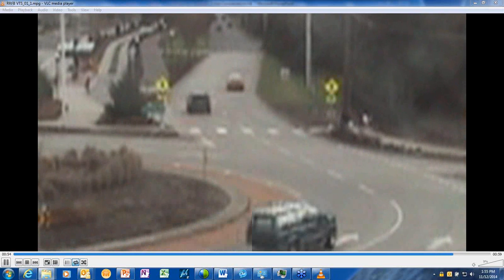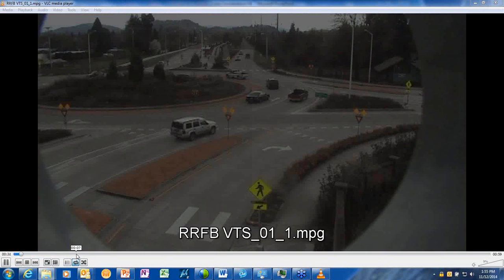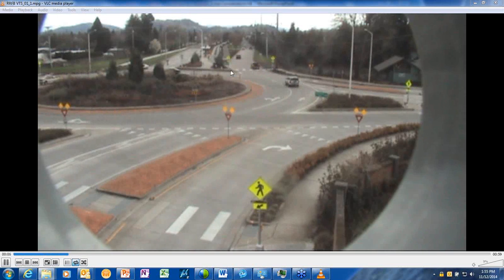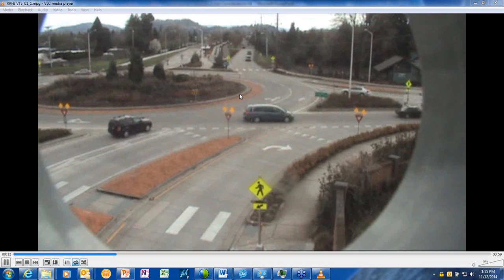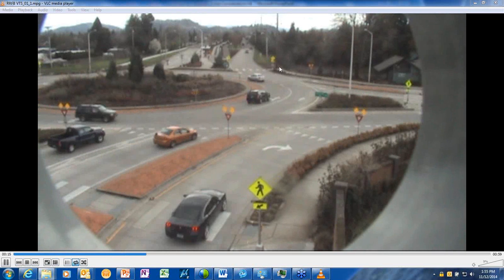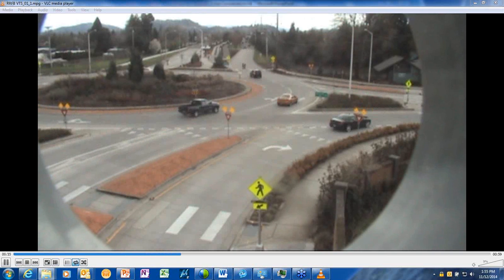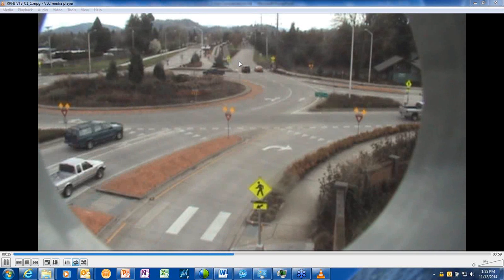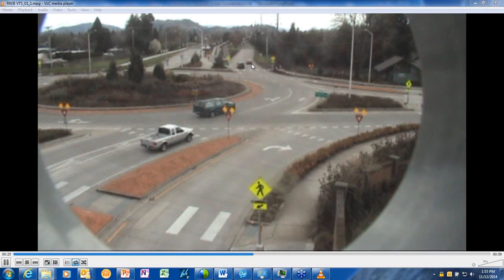The difficulty with this device is its location proximate to the roundabout, how close it's located, whether it's in the conventional crosswalk location or if on the exit it should be displaced. I don't have this video handy, but I have another clip of video from the ground level where the pedestrians are not pushing the button, or if they are, they're just walking without looking at the traffic. And traffic comes from the roundabout and is dealing with the turning movements and other vehicles, and the driver just looks up and almost hits a pedestrian. So again, more devices doesn't necessarily improve the safety of pedestrians.